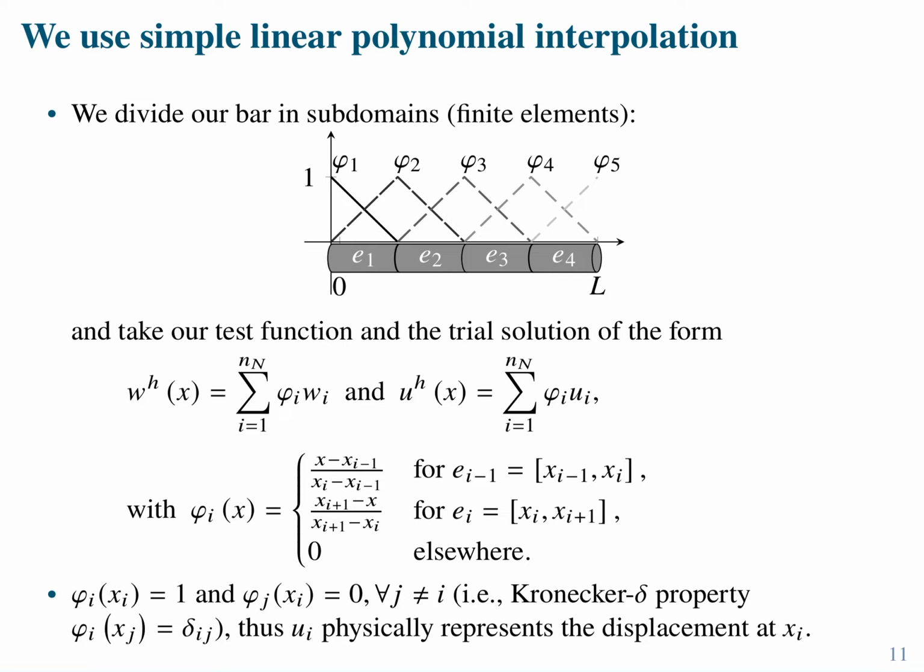But it's a 5 by 5 system. We have 5 degrees of freedom. It's just that we know the value of one of them. So indeed, eventually, it's a 4 by 4 system that we have to solve. In fact, computationally, normally we don't do it like that. We do something to the matrices so that you're still solving a 5 by 5 system. It's more efficient. Instead of separating the matrices in parts that you know and you don't know, normally we modify the original system and we end up solving the original size. But Alejandro, that is very inefficient. No, not really. The boundary conditions are always applied to a lower dimensional manifold, which ends up being a very, very small subset of degrees of freedom.